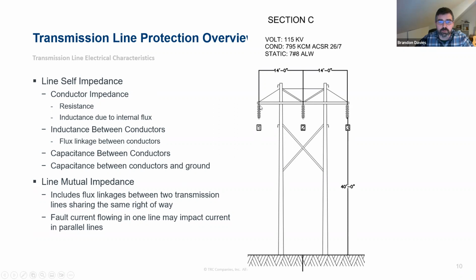So usually what you'll see is these bell style insulators that will be hanging off the structure itself. They're set up that way so that water drips off of them and down, and doesn't create a continuous path of water across the insulator that you could arc over.